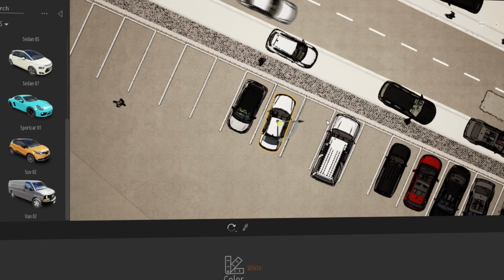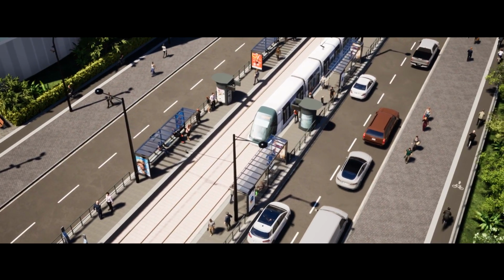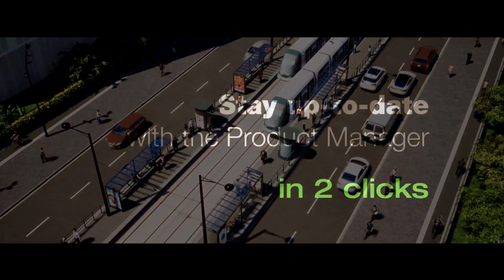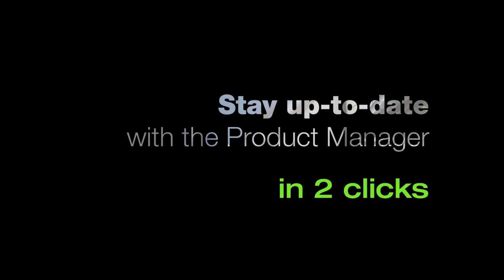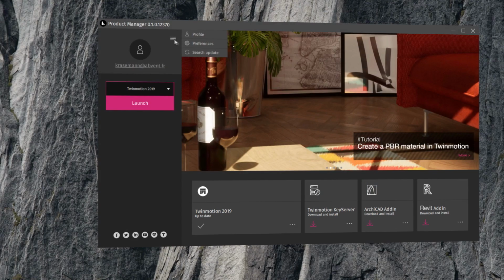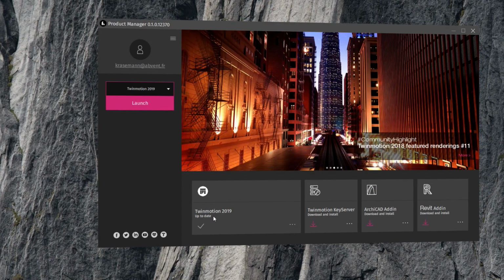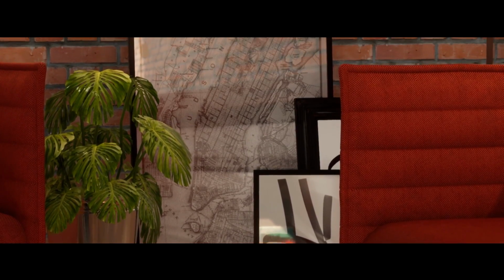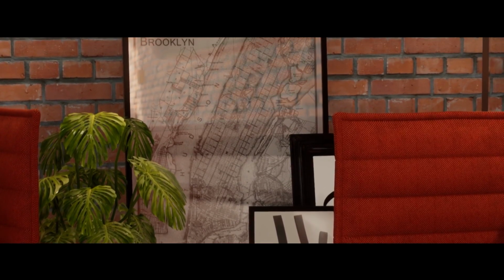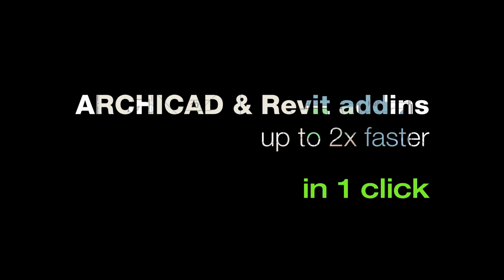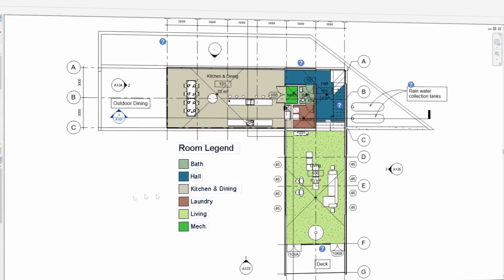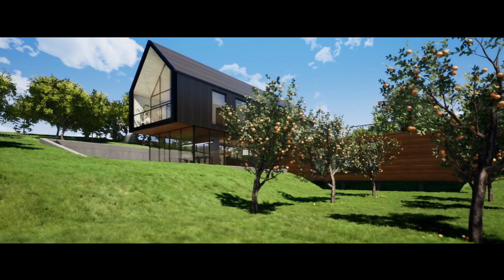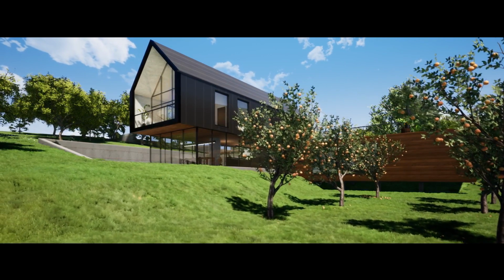But you can open your Atlantis file in Twinmotion, so you can place all your objects inside Atlantis, open them directly inside Twinmotion and save them inside your user library. It's a bit of a long process, but you can retrieve all your Atlantis objects inside Twinmotion. It's possible, but it's not possible to download these objects directly from the Atlantis library into Twinmotion.